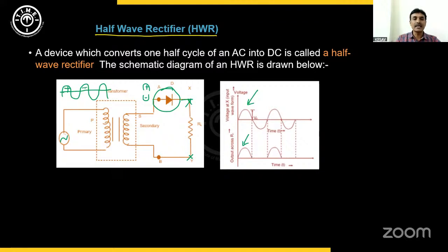And next, another positive half cycle comes into picture. So that will pass through it. This negative part is missing. That's why you have a blank in this region. And again, positive half cycle passes through the diode, and this negative half cycle is not passed. Understood? What is a half wave rectifier? Half of the wave gets rectified in this.